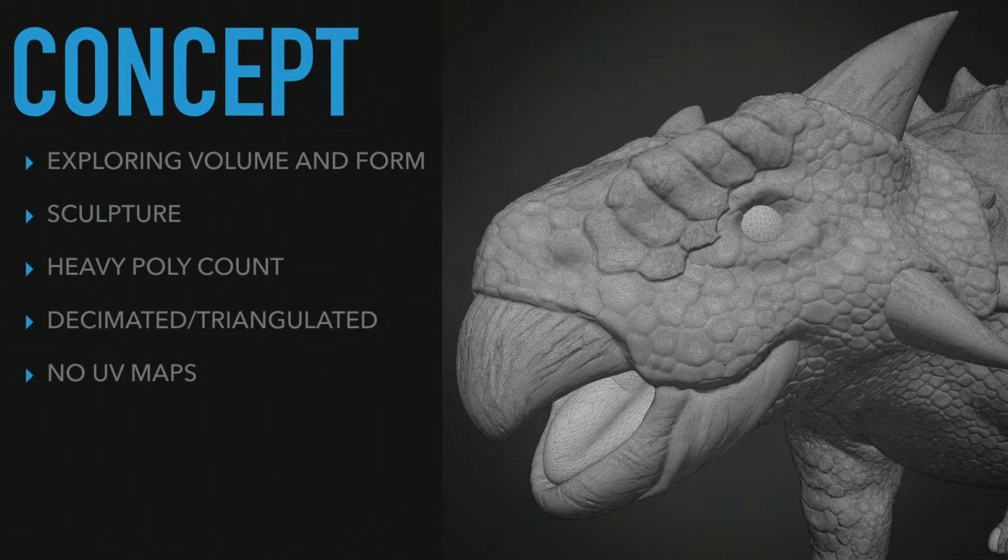But look at the geometry in the eyeball. It's really packed in there. If I want my character to blink, I can't do it with this model. The triangles and the structure of the geometry are physically going to stop me from doing that. It's not even possible with this version of the mesh. If I wanted to texture the face or even get some information in the eyeball, I can't do it with all those triangles. The process is physically going to stop me.